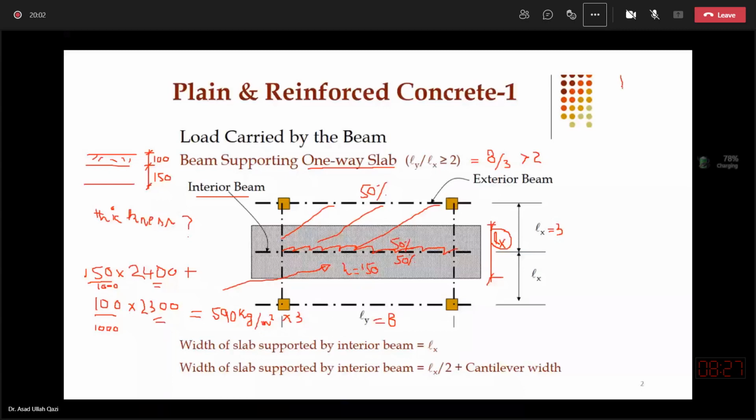So based on the structural use information regarding the type of the building, what kind of occupancy we must select, we can decide the live load. Suppose it is an ordinary residential building, and for such buildings we can check from the guidelines what the live loads suggested are.